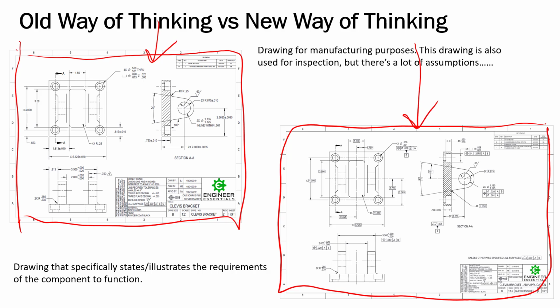And like this drawing shows over here on the right, this is directly at the true function of this component. A being the bottom, and then the bolt pattern actually attaching it to that air cylinder. That shows that exactly. And the datum reference frames are really what come back and call that up and show that that's truly what it is.